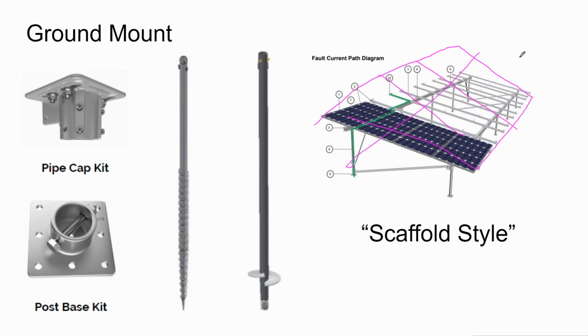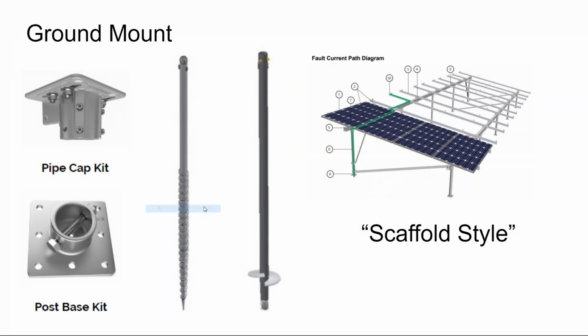I think they're kind of like giant satellite dishes where the owners and the installers are really enthusiastic, but they won't really stand the test of time. I also think that the bleacher style makes maintaining the ground underneath it kind of a hassle because you can't really mow underneath the array or even walk or access underneath the array very easily.